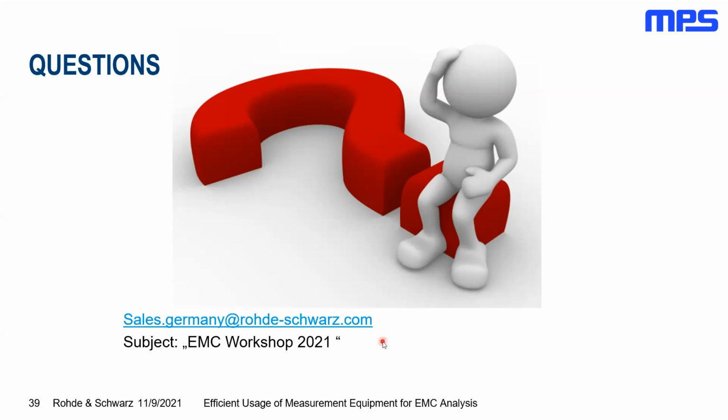Thank you very much. So the next question is, can you spend a few words on the VBW setting related to the RBW 9 kilohertz, 120 kilohertz setting? That's a good one and a very tricky one. So the RBW filter itself is the filter which is mounted in our mixing stage. So when we're doing the analysis, if you think about the block models, then we have there the resolution bandwidth